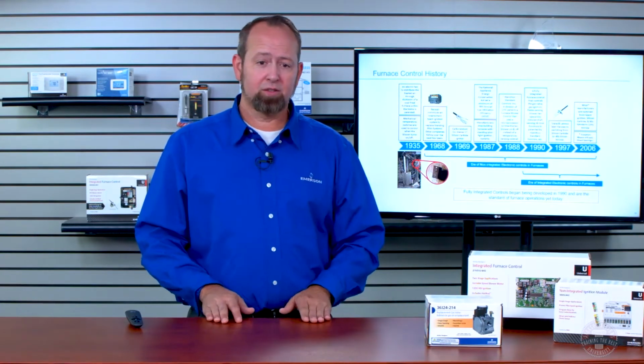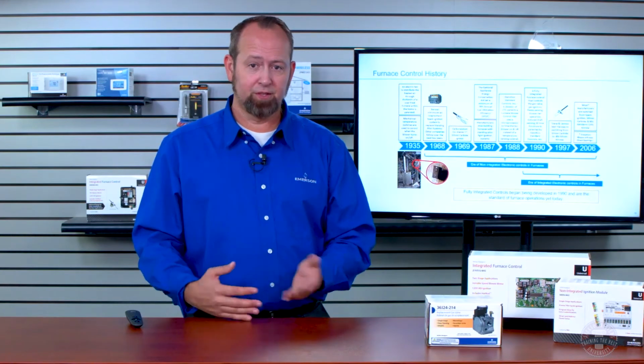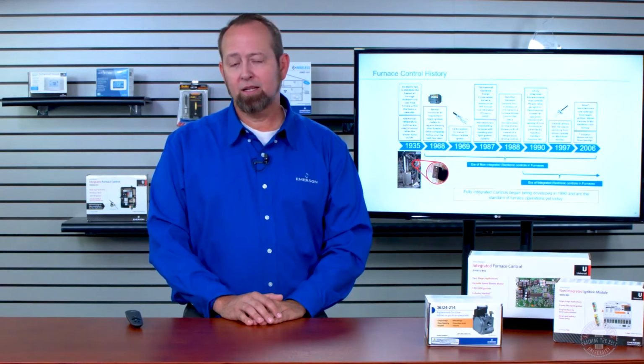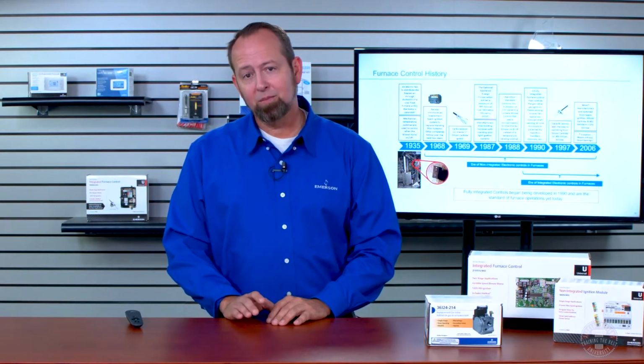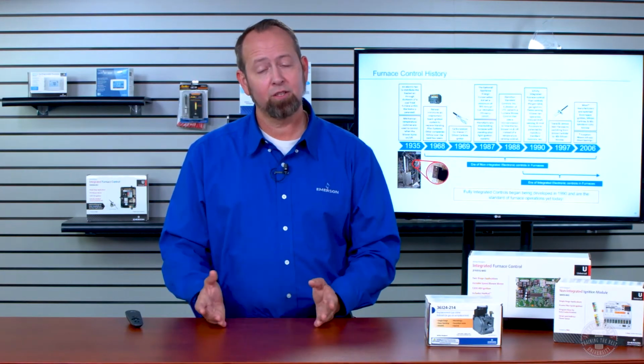And I went out, got the model number off the furnace, figured out what the igniter was, and replaced the 80-volt igniter in the furnace. And it didn't last the year. I went back out for a no-heat call again and found that this 80-volt igniter had already failed. So I got the model number and serial number of the furnace, and I got the part number that was on the IFC, or the control module, the control board, excuse me.